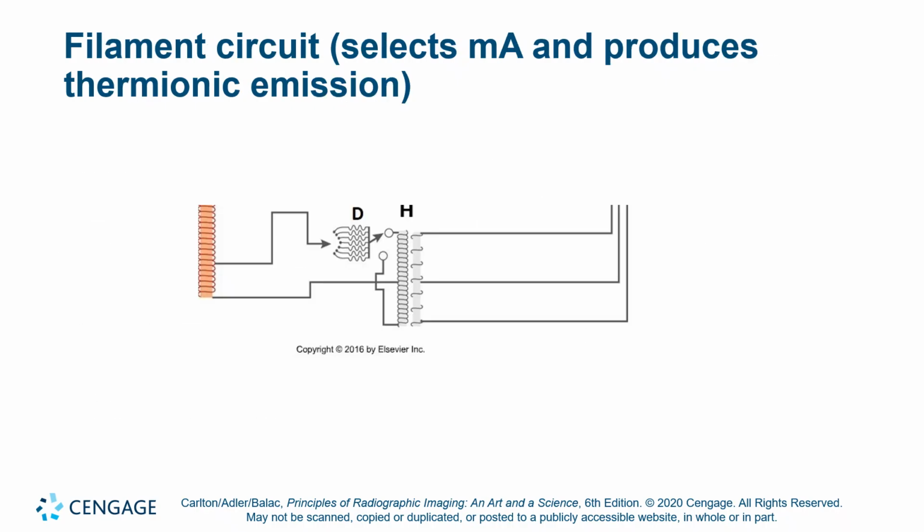All right, here's our filament circuit. This is a static takeoff from the autotransformer over here on the far left. So that means we have a fixed output voltage rather than a variable output voltage on this bottom circuit. Okay, and then we're going to head into the rheostat where we manipulate Ohm's law at part D. That is our rheostat with a multi-point switch. Okay, and so we got a fixed voltage and a selectable resistance.